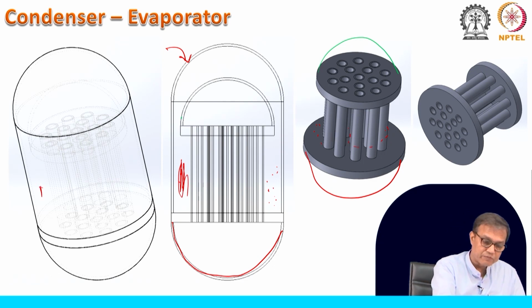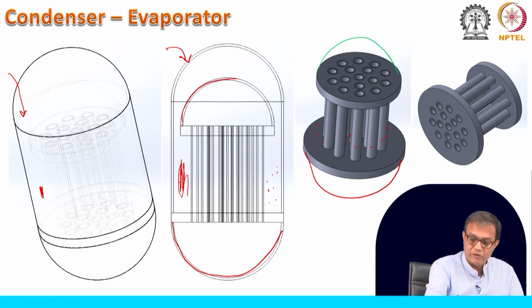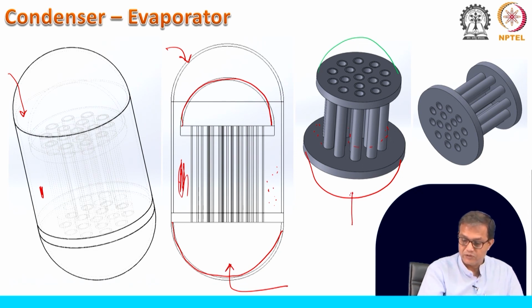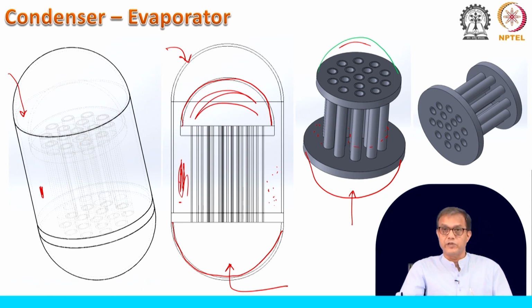So, in this space we were filling it up from this part, and in this inner part the high pressure gas is coming over here, passing through these tubes, and getting collected over here. This gaseous part will be collected over this part, and the liquid refrigerant part is on the outside of the tubes. So, they are not getting mixed with each other.